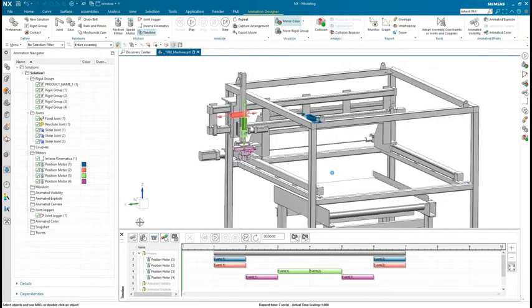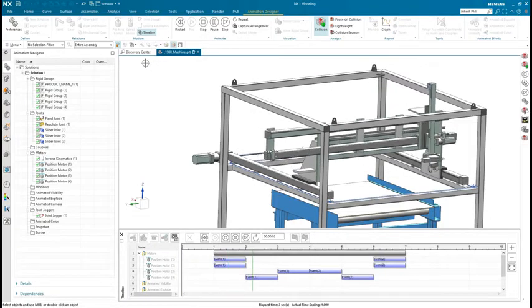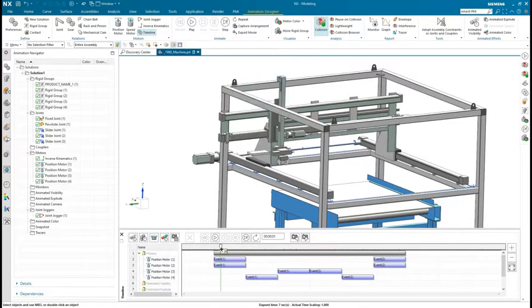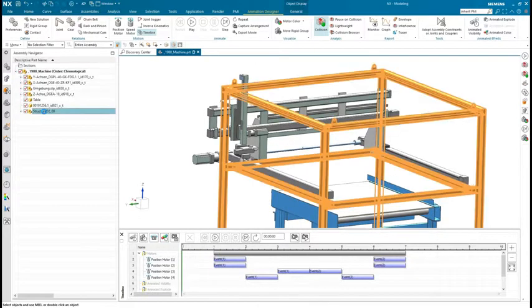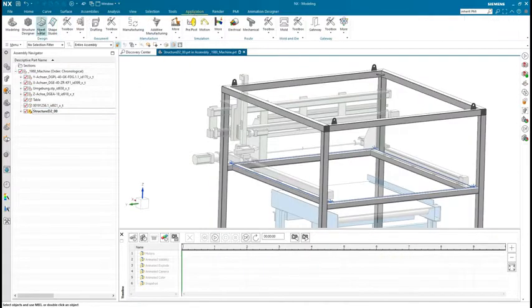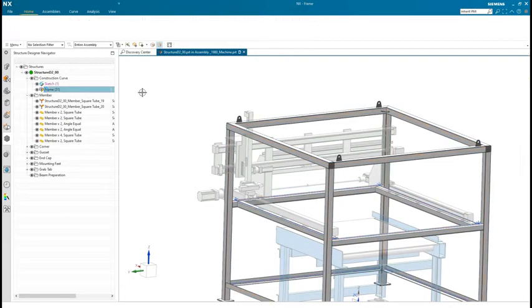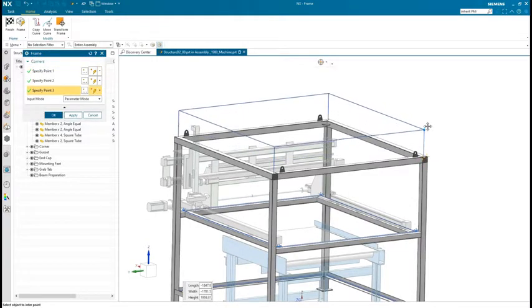Now that we're certain of the articulation, we can analyze the assembly for interferences between moving parts. Any parts highlighting in red indicates an interference. While we're not so worried about the interference near the end as we selected an arbitrary destination point, however, the plunger hitting the frame must get fixed. Since all these applications are tightly integrated, all we need to do is adjust the frame's cage. We'll drag the upper point a bit higher to allow clearance between it and the moving component. Once complete, all parts update to the new size.